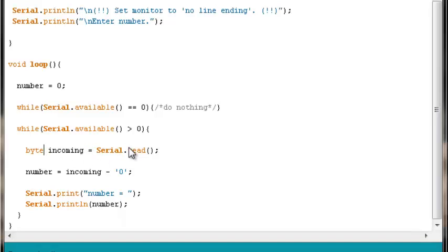So what happens is the first byte's read, it's stored in this variable, then we get to this point, and this is where that ASCII code, we're removing it or converting, pulling off the amount necessary to convert the ASCII type character that we've received from the serial monitor into an integer type variable. Number is an int, so it's going to convert the incoming byte, it'll be a single digit at this point, into a true single digit that's of the integer type.